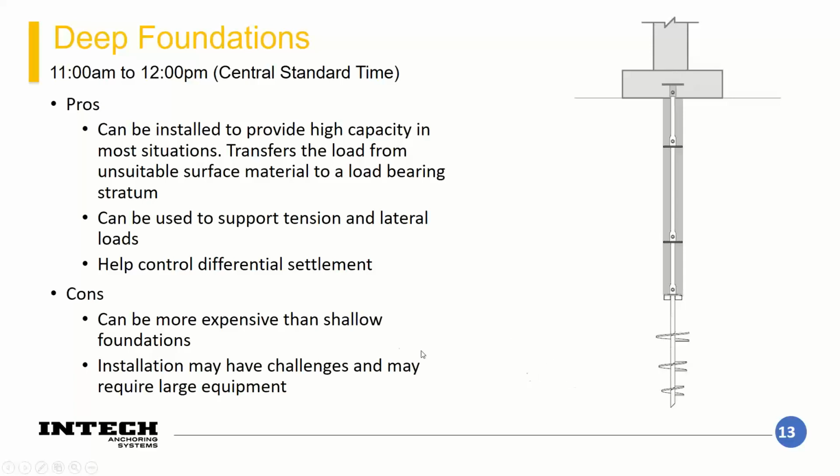So the other thing is, depending on what type of deep foundation you're using, you may have installation challenges, whether that be due to difficult soil conditions or just headroom conditions at the site. And then you're also going to have large equipment for some of these different pile types.